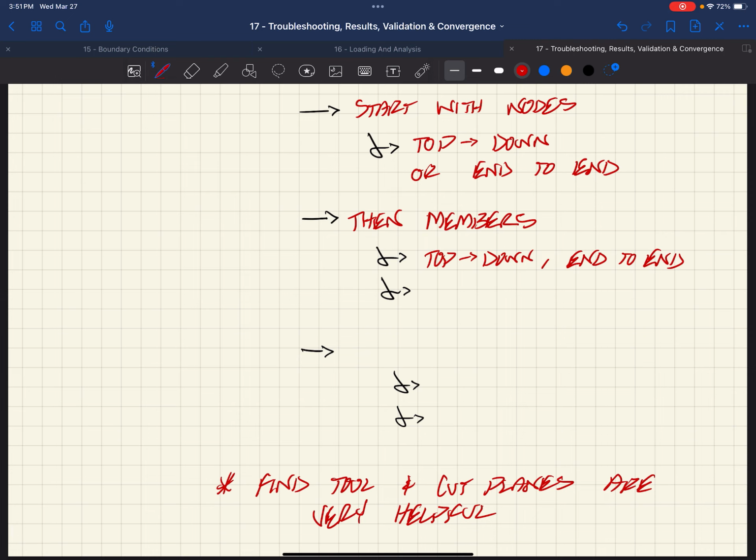In members, there's a bit more to members, right? Members have geometric properties, they have material properties, right? You can also dictate whether a member is a column, so a vertical element, a horizontal element, a beam, or a diagonal element, a brace. And those designations have implications or I guess, ramifications in VA relative to how load is distributed. I'll let you guys dig into that whenever you get to it.